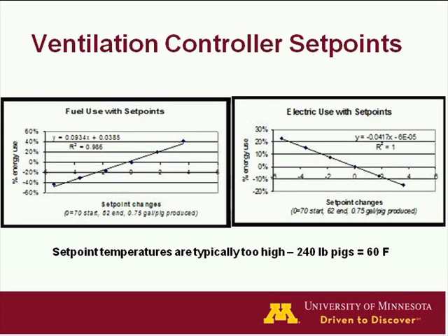We don't want to get those too high, otherwise we can actually use excess energy because we're maybe using more fuel, LP gas, if it's set too high for the size of pig, or if it's set lower, we'll use more electrical energy because there will be more fans running. So again, there's a compromise.